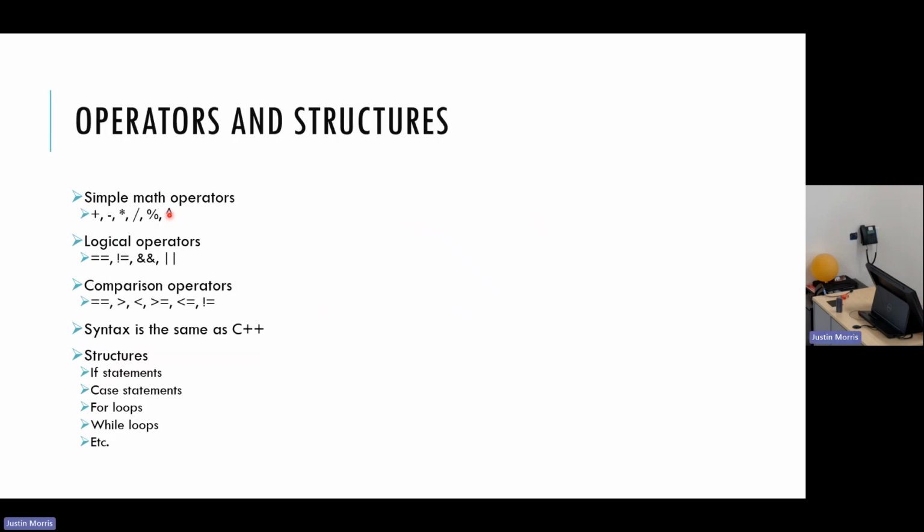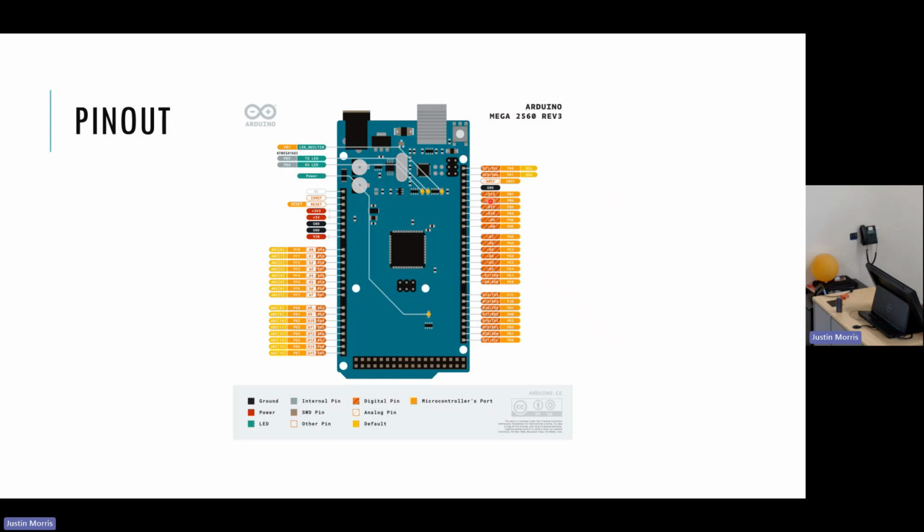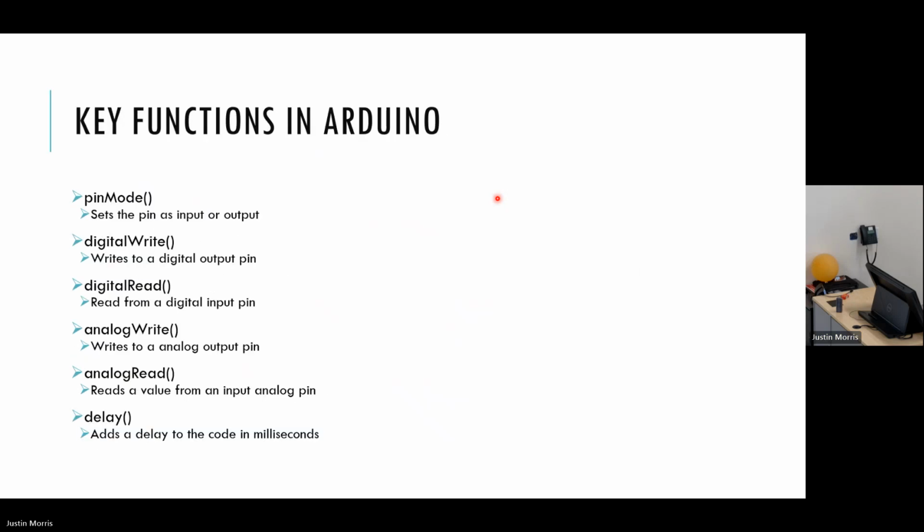So if you connect your sensor to pin 13, so D13 right here, you would then use pinMode, and it's a sensor, so the pin mode would be input, right? And then in terms of the pin number, it would be 13.